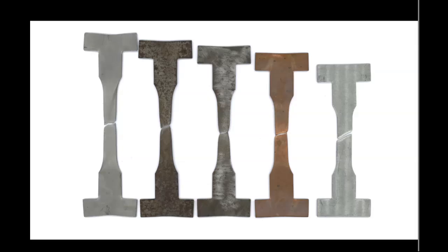Well, not really, but if you contrast, for example, aluminium and stainless steel, what you see is that aluminium is a weaker material and it has inferior elongation, longitudinal, and inferior reduction in cross-sectional area, so it does not really shrink. So it's a brittle material and it's a weak material. This is something that you should be able to identify. Contrasting to stainless steel, it is a stronger material which is more ductile.